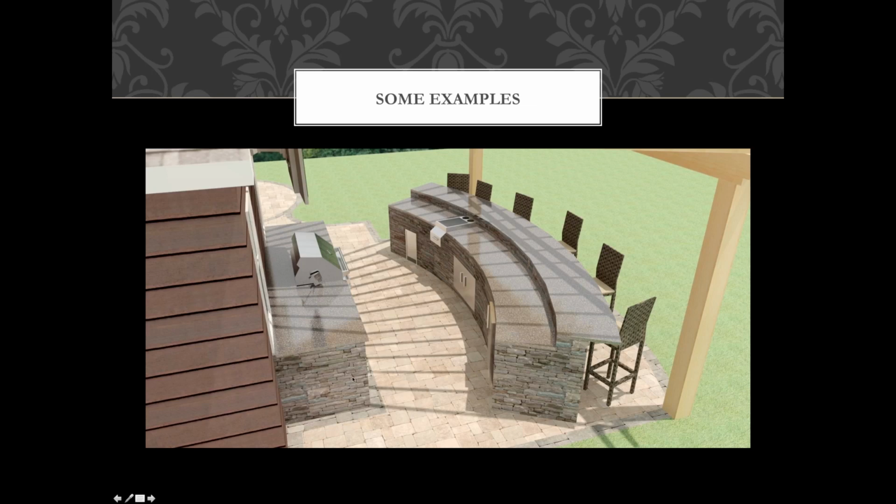Here we have a scene that I just built in SketchUp, applied the automatic textures, and clicked render, and this was the output image. You can see reflections and stuff like that. But one of the things to watch out for is in SketchUp, when you model arcs and curves, they aren't true arcs and curves. They're made up of straight line segments. So if you have curved surfaces, you'll have to increase the number of sides, so that it doesn't look like all these straight line segments in there.